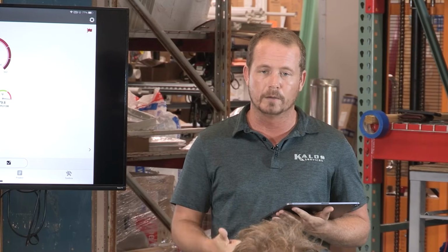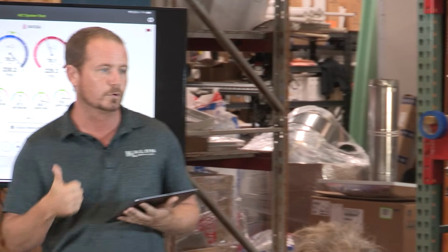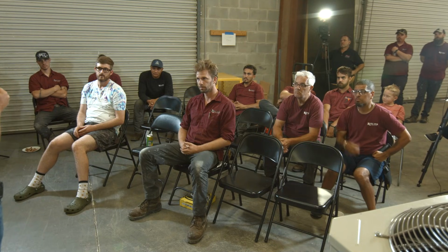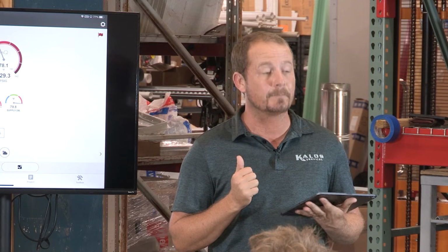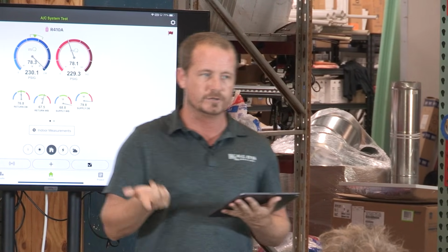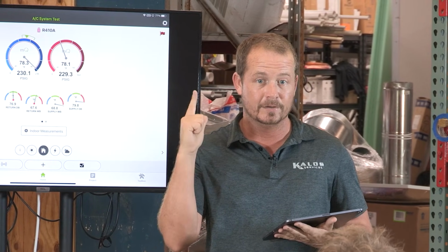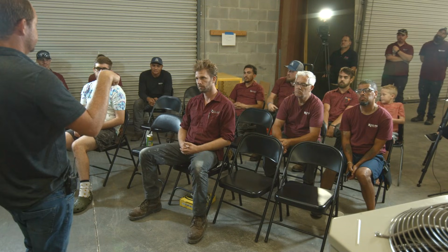What is our number one primary refrigerant side indicator of low airflow, regardless of system type or metering device? Low superheat. Low suction line temperature. Low suction line temperature is actually a great indicator. I actually prefer that over superheat, because a TXV is going to hold your superheat where it's supposed to be, right? That TXV is going to start throttling. But your suction line temperature is still going to be low. Why? Because you're getting liquid refrigerant.